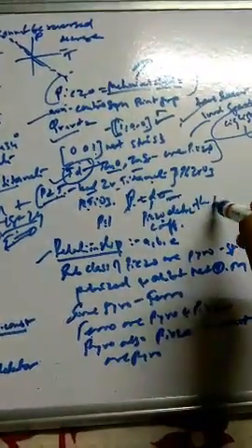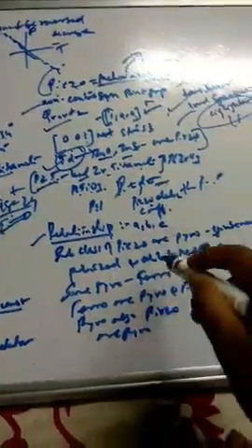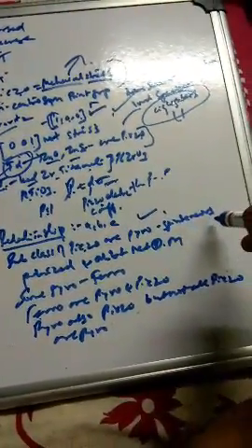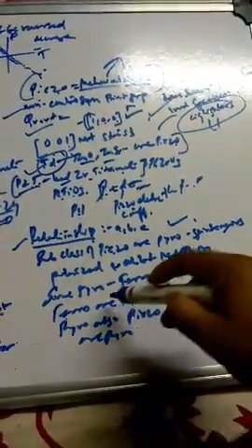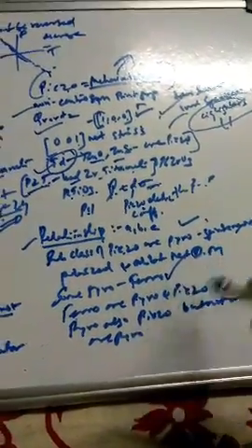If you look at the relationship between ferro, piezo and pyro, the pyro materials are a subclass of piezo, so they also act as piezo. Spontaneous polarization is observed here. Some of the pyro materials act as ferro, but ferro materials are both pyro and piezo.